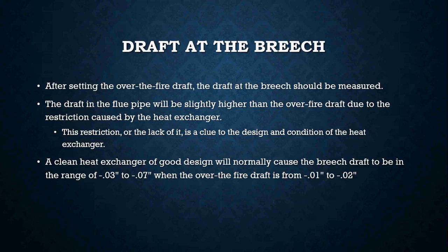Draft at the breech, or in the flue pipe. After setting the over-the-fire draft, the draft at the breech should then be measured. This is your second reading. The draft in the flue pipe will be slightly higher than the draft over the fire due to the restrictions caused by your heat exchanger. This restriction, or lack thereof, is a clue to the design and condition of the heat exchanger.